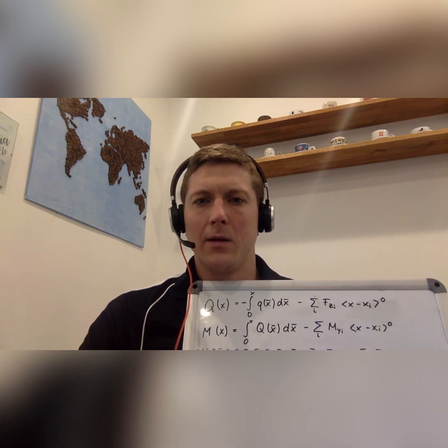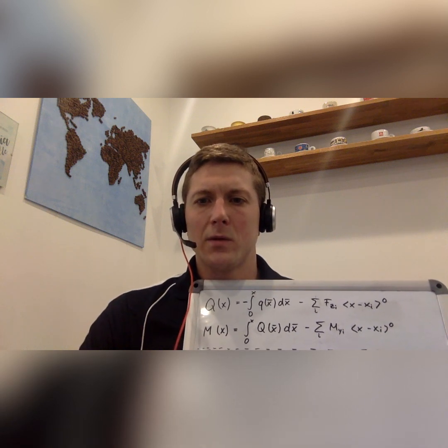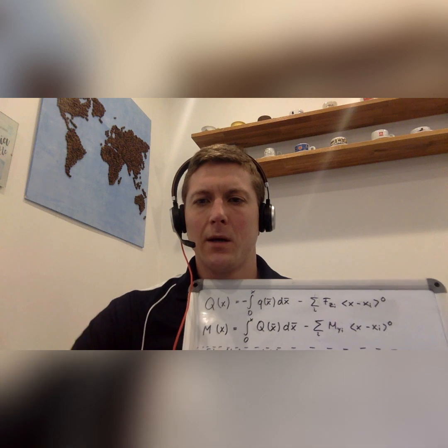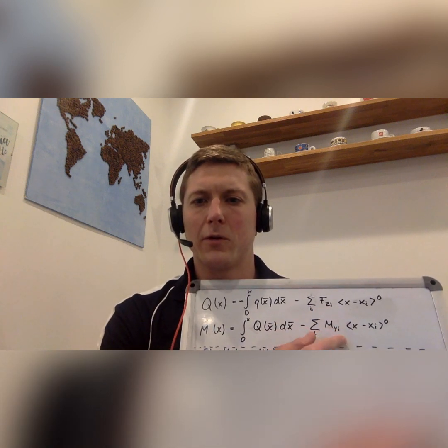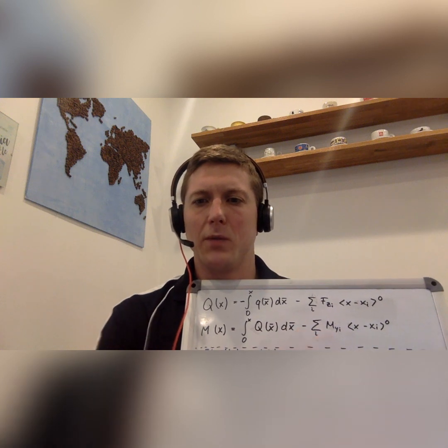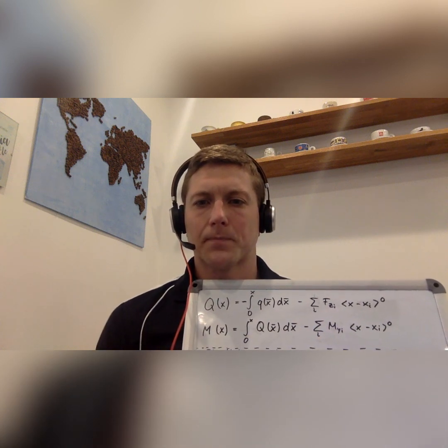And by this method, it was possible to determine all bearing reactions in advance and then use these forces and moments in our integration scheme, where we had the discrete forces, also the bearing forces, and the discrete moments, which would also be the bearing moments.